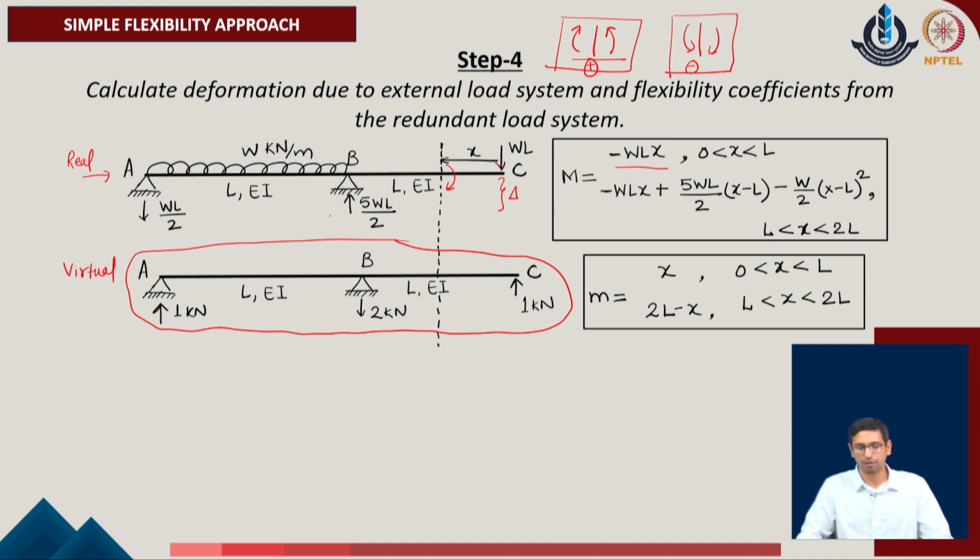With this point in mind, we understand that between the span B to C, the moment distribution can be described by this expression, whereas once you move to the given span over here, somewhere at this position, the distribution of the moment will now also be affected by the reaction load appearing from the support at B and the uniformly distributed load of the given system, and that has also been identified over here.